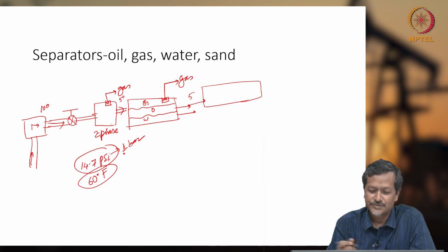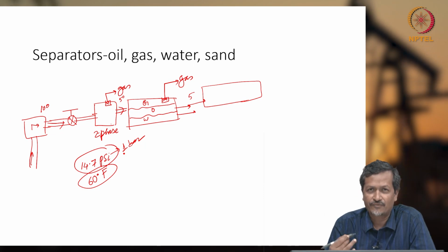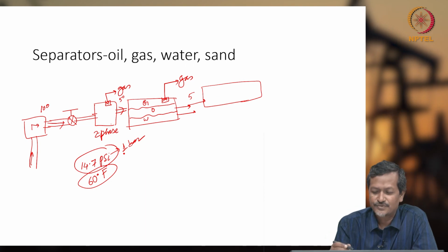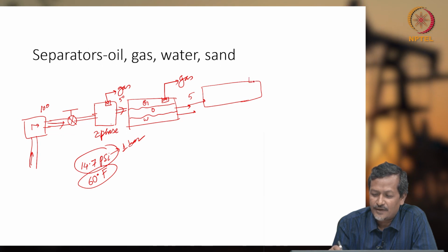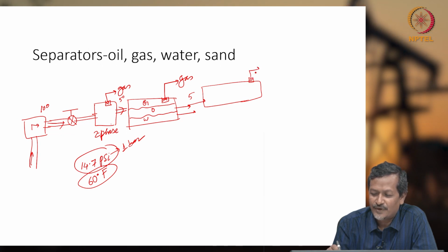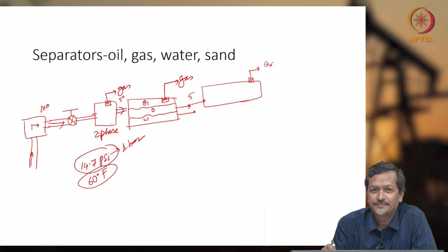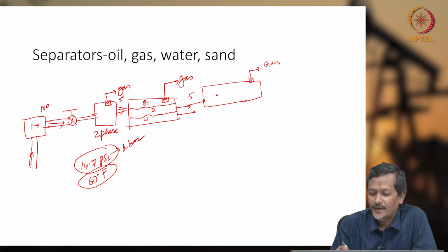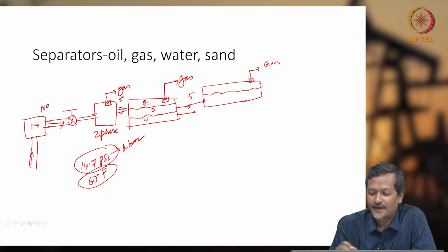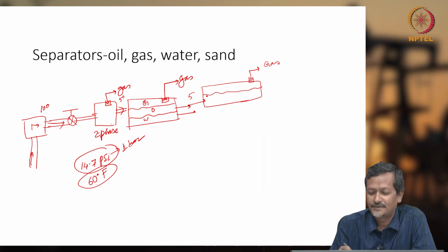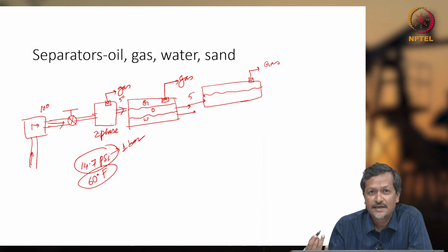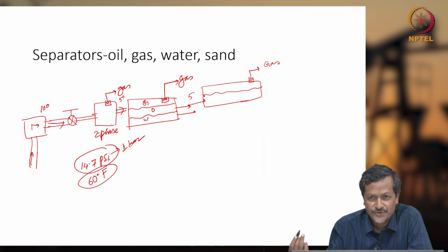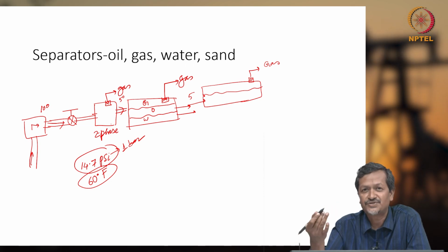Okay. So, let us say there is still 5 bar pressure, or about 72 psi. In that case, you put the oil in another separator, and you put a mist extractor here, and you take gas out, since some dissolved gas will still be there, right. Now, you have oil here and you want to separate water. How to separate? Sometimes you may have to add chemical, or use a heater treater. Heater treater means you increase temperature, so that viscosity can be changed.